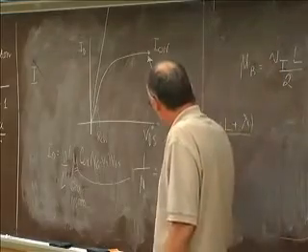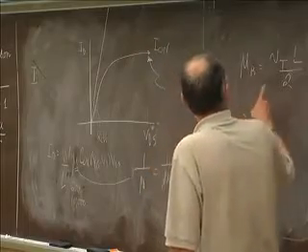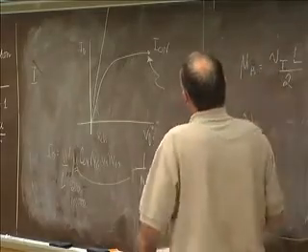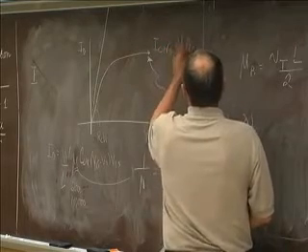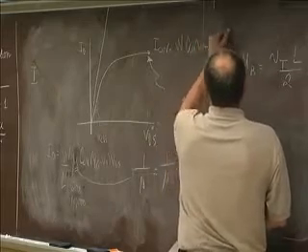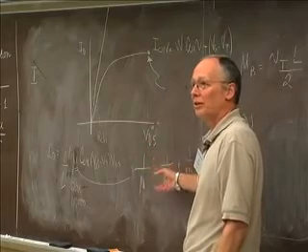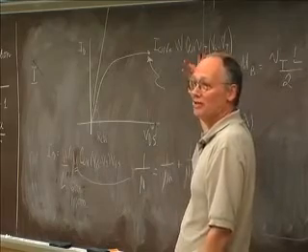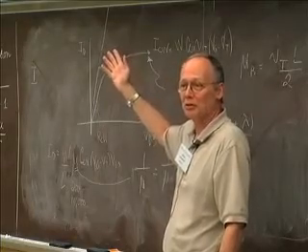If I have a high mobility, I have a very light effective mass. That light effective mass is also going to give me a very high thermal velocity. Remember what the on current was: W times Cox times the ballistic injection velocity times Vg minus Vt. So what's giving me the high mobility, part of it is due to low scattering, part of it is due to the light effective mass. The light effective mass is also giving me a high injection velocity, so that's boosting my on current. That's good. I'll have a higher ballistic limit in those materials.